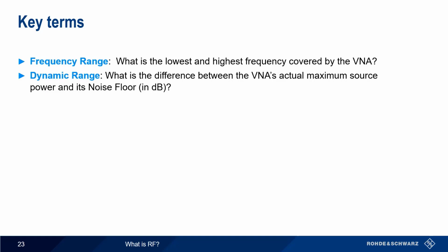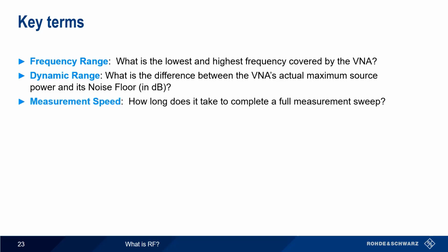If you need a wide dynamic range for a production application, you may have to sacrifice noise floor by using a wider IF bandwidth to maintain an acceptable sweep time. This might require a higher performance instrument to meet these conflicting needs. Measurement speed is intrinsically linked to your dynamic range requirements. Banner specs for sweep speed are often provided for wide IF filter settings. Also, check the fine print. Are the sweep times mentioned in the specifications based on a 1-port or 2-port calibration? Make sure you consider the values that coincide with the needs of your application.